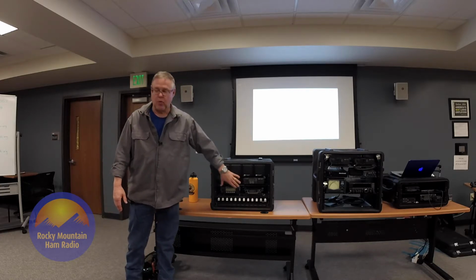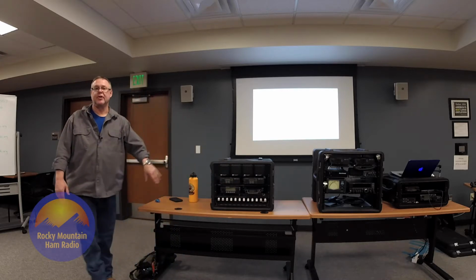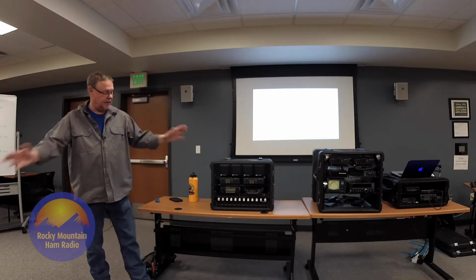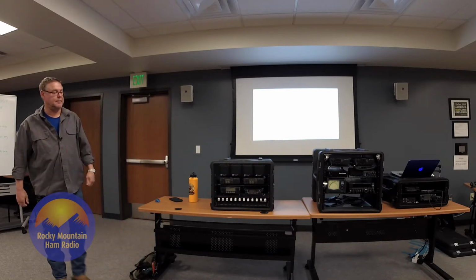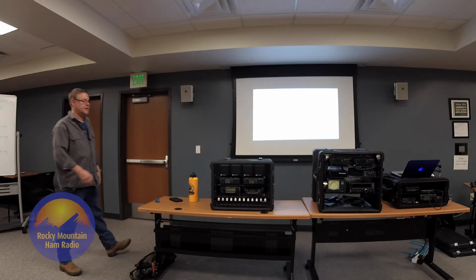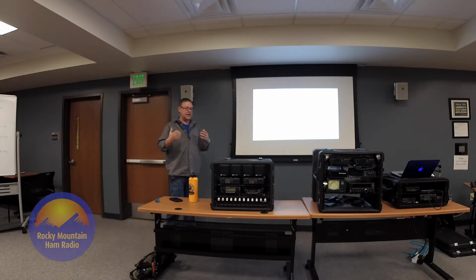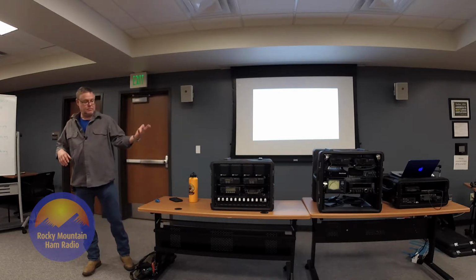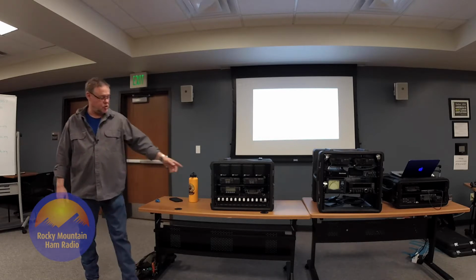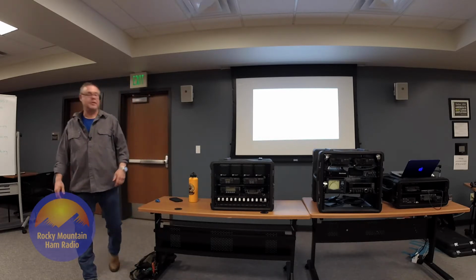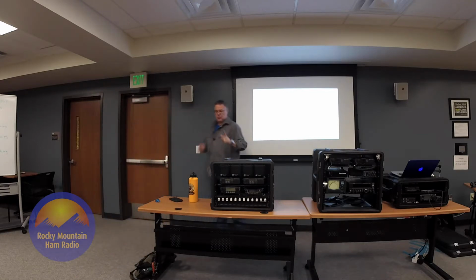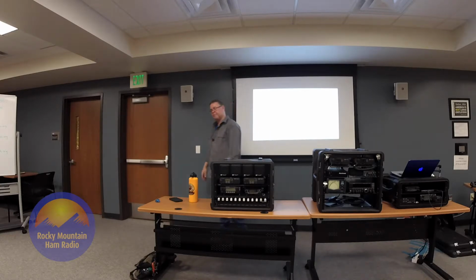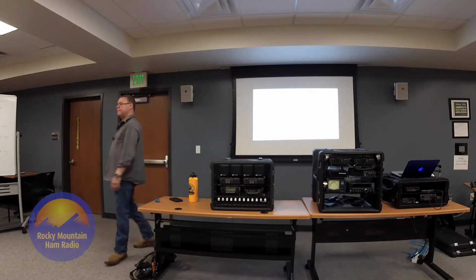Everything is managed and is one piece, and it's built outside this compartment. So this thing's sitting on a workbench. I mount all the brackets, all the radios, all the cables, I zip tie them all down, strap them all down, interconnect everything, and then strap everything down again. Then I slide it in there and try to hold it up or have someone hold it up, start the screws and then screw the screws in. That's how it's built. And then you come around the back and you'll just have little pigtails to the antenna, to the speakers, to the power poles, and that's how we build them.